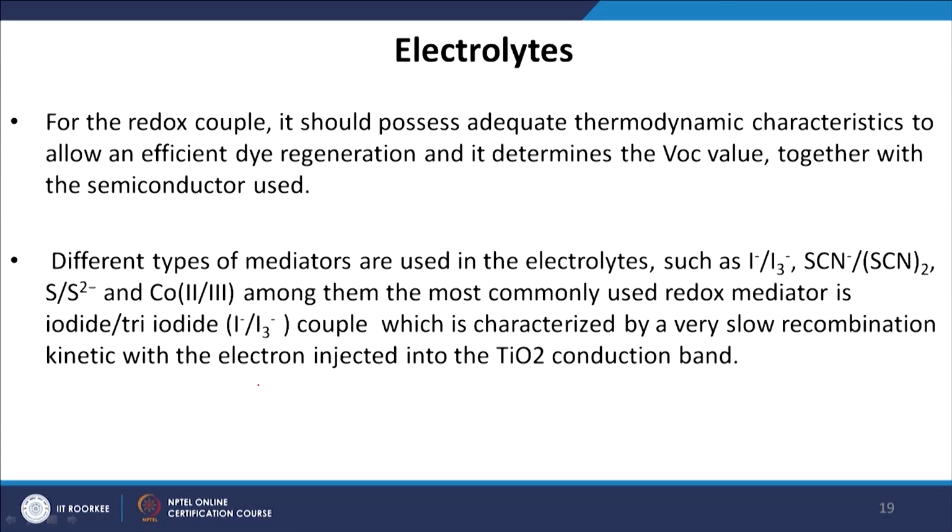Today's lecture we will discuss the different conditions for fabricating the electrolytes, how we choose an optimum electrolyte for a DSSC device, and at the same time what electrolytes have been used in the DSSC device. The redox couple should possess adequate thermodynamic characteristics to allow efficient dye regeneration, as it determines the VOC values together with the semiconductor used. So basically the electrolyte along with the semiconductor determines the VOC value of the device. So it is very important to choose what kind of electrolyte we are picking.